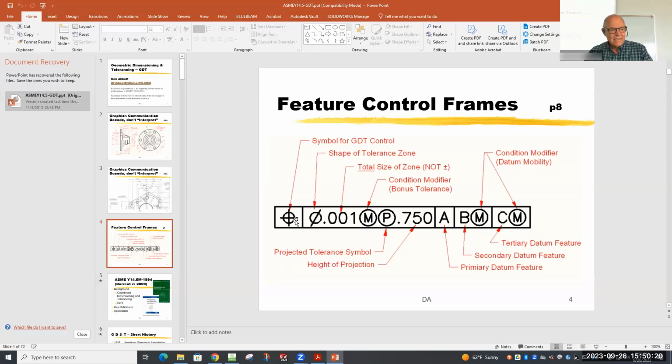In this particular case, it's something called positional tolerance. And positional tolerance means this. If I have things that have to line up, the holes have to line up. If the hole that I put in this part is exactly the right size, but it's not in exactly the right position, and I try to take these things and match them up, and two of the holes don't line up quite, I can't put a bolt through it. So positional tolerance is what controls the location of those holes as well as the size.